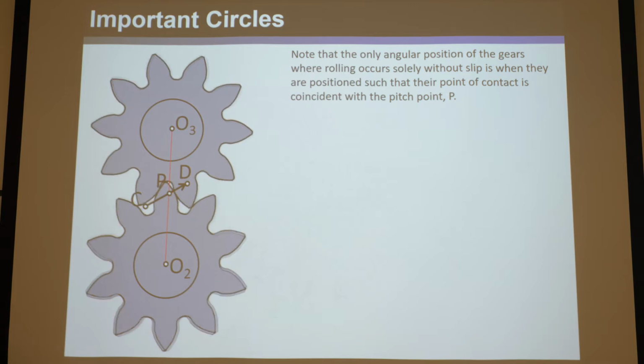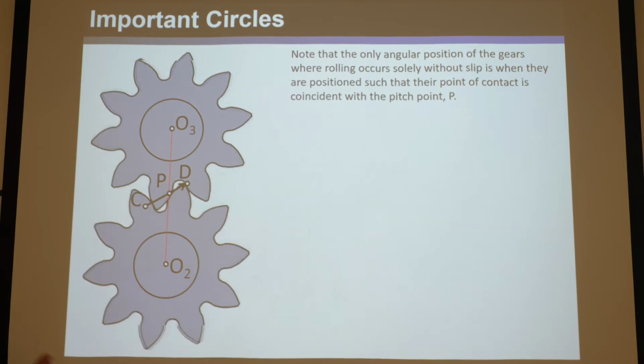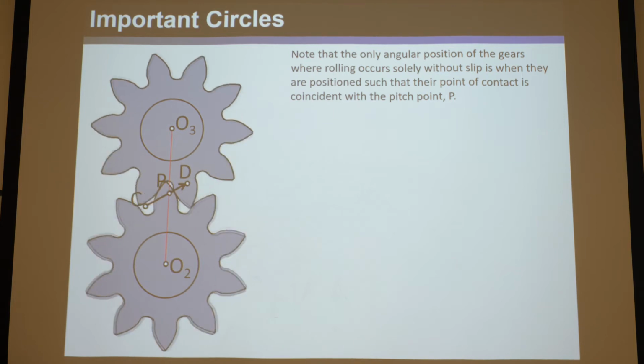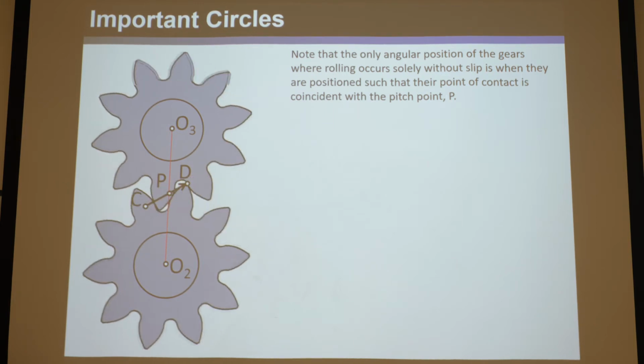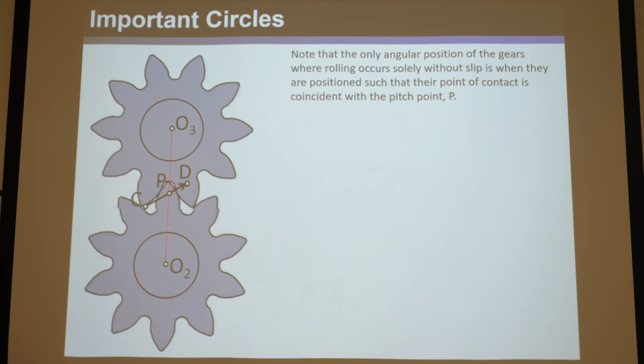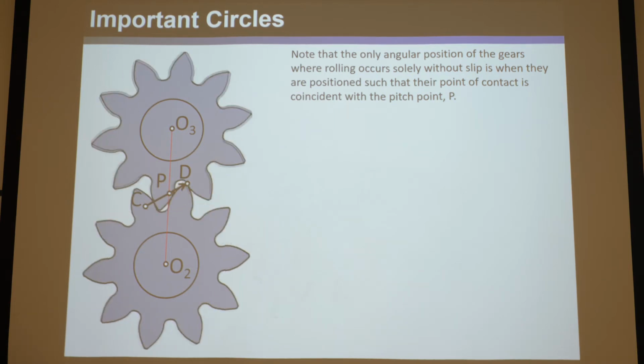So anyway, that's some complexity there. The truth is they're sliding and rolling, but we model them as if they're only rolling, and they certainly only have 1 degree of freedom, because the teeth can't shear off from sliding.